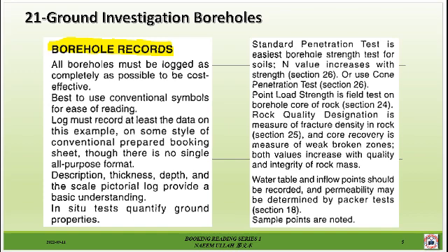Point load strength is a field test on borehole core of rock. This we will discuss in section 24. Rock quality designation is a measure of fracture density in rock, and we will discuss this further in section 25. Core recovery is a measure of weak broken zones.